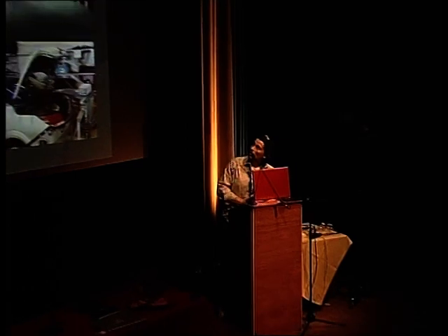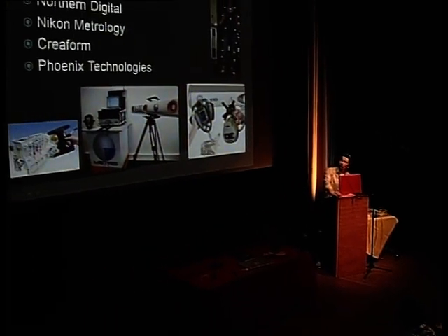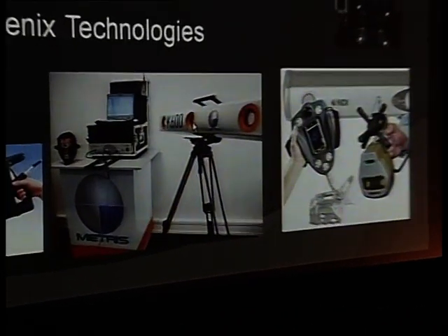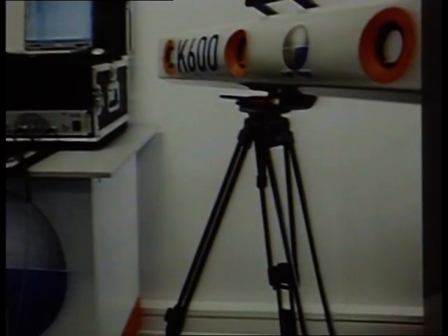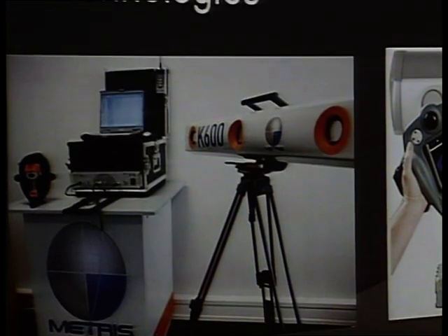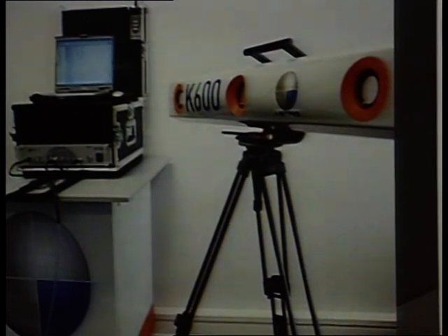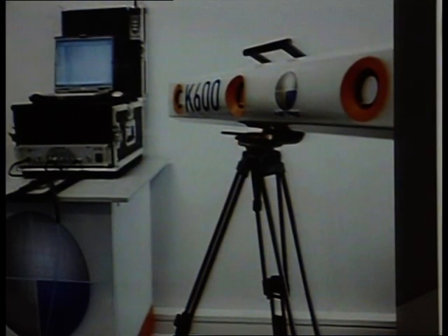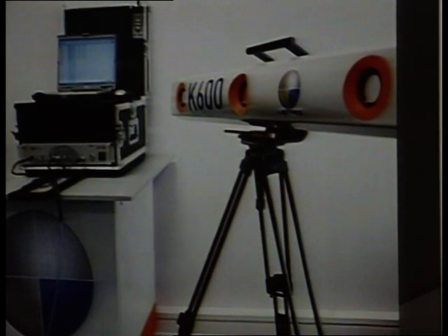Well, the design of the type of trackers that we work with is such that it's pre-calibrated. There's a carbon beam inside, all three CCDs are glued to it, and the whole thing is calibrated using a huge CMM with a huge volume. Once you have done that, you don't calibrate the position or the focal length or whatever of the cameras anymore. You leave it like it is. The only thing you still need to do is compensate for temperature fluctuations if your measurements require traceable accuracy.